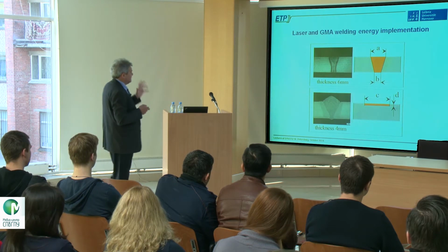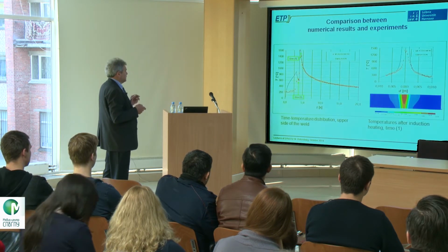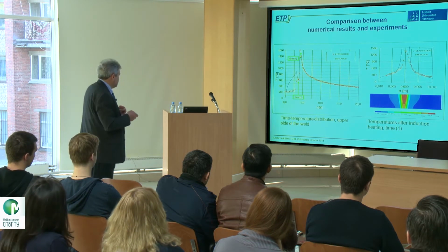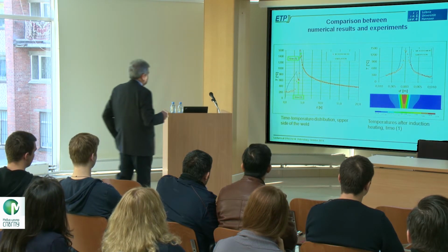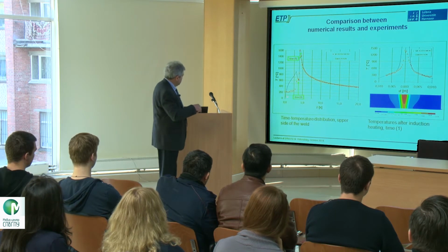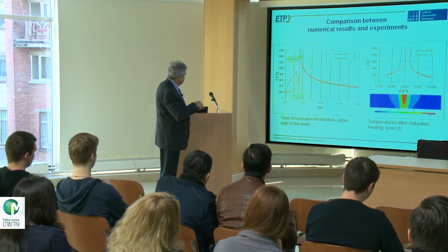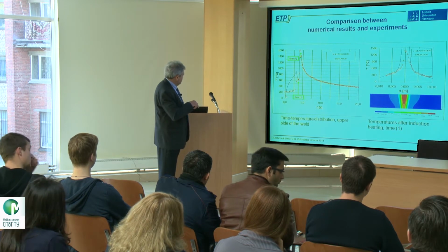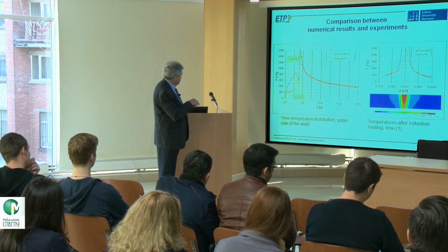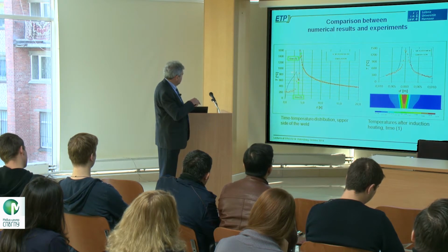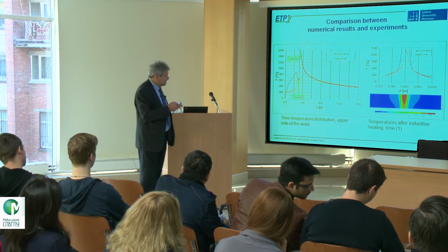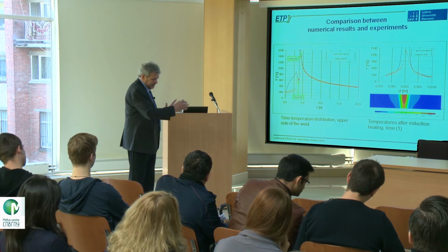So we implemented this in our model, and so we then could really simulate the whole process. And here you see one diagram over time. The workpiece, the seam is coming in, then it's heated by induction, and you see here up to around 900 degrees. Then we have a small gap, as you could see, between the inductor and the laser.